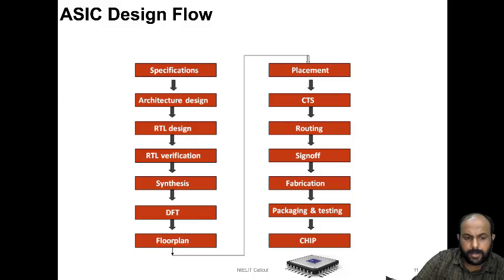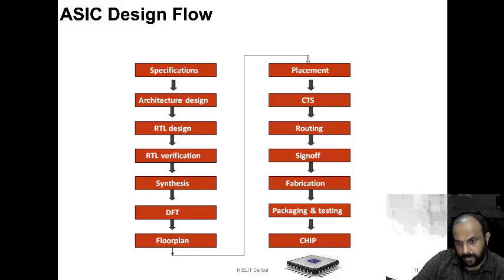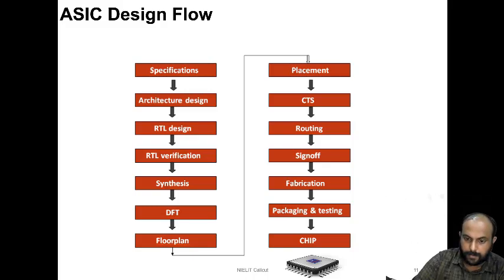you can see here, including synthesis, DFT, which stands for design for testability insertion, floor planning, followed by placement, and CTS here stands for clock tree synthesis. It is followed by another step called routing, then design sign off or design verification, then fabrication, packaging and testing.